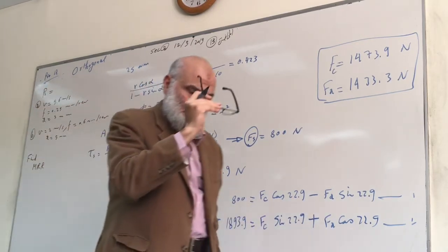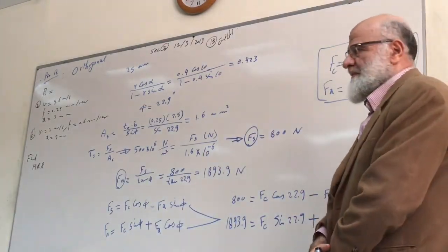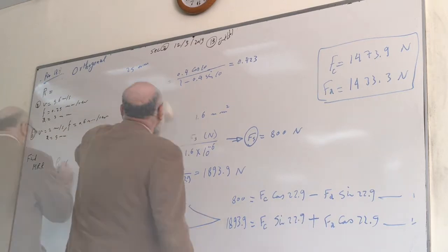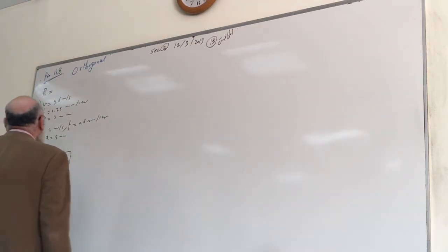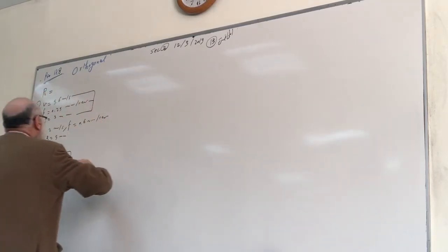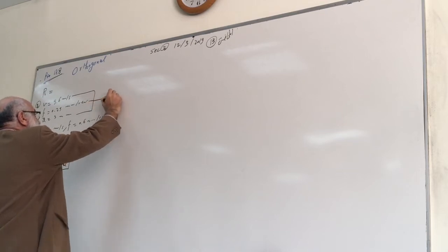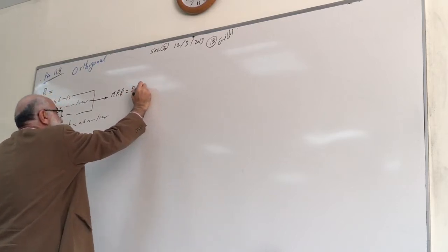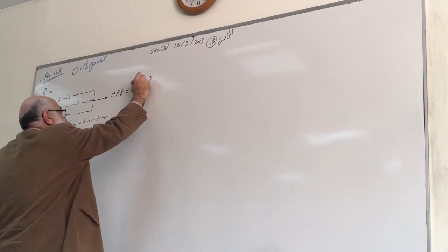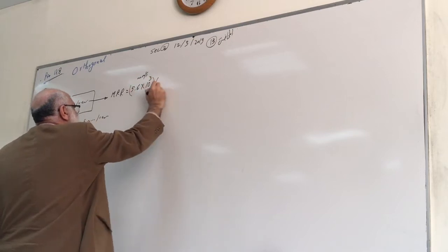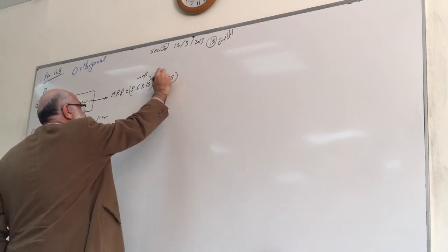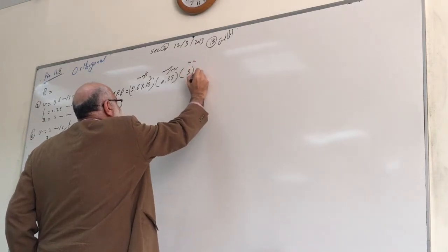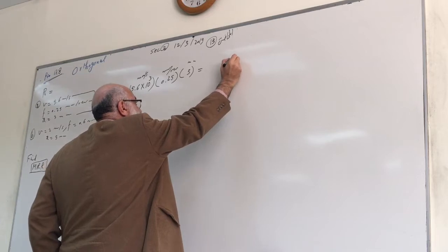So we will solve the problem twice, as if it were two problems. Multiplication of all of these three values gives you the MRR: 5.6 meter, make it millimeter, millimeter per second, multiply by the feed 0.25 millimeter per revolution, then 3 millimeter. That will give you millimeter cube per second.